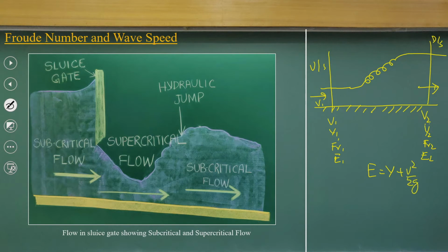So, we can compute the specific energy upstream and downstream. Because of the hydraulic jump, as I emphasized, energy losses happen.